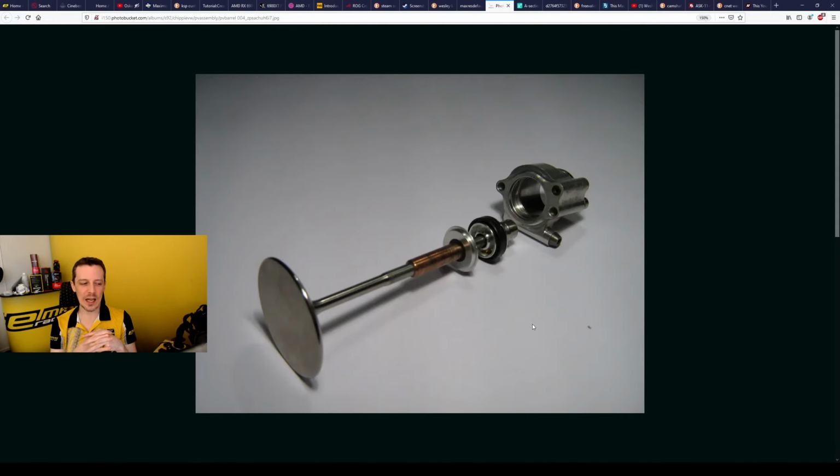But yeah, you probably might need Inconel or stainless on the exhaust side. And then of course, sodium filled is like the ultimate badass of cooling valves, especially for race engines. You have this large flat surface area in the combustion chamber that receives a lot of heat, and then you have the exhaust gases flowing past the valve. So there's basically no cooling at all.